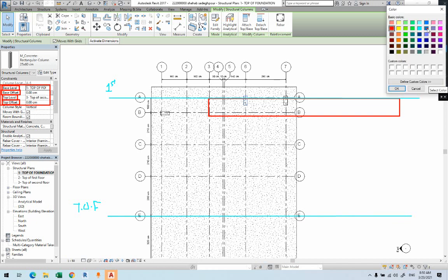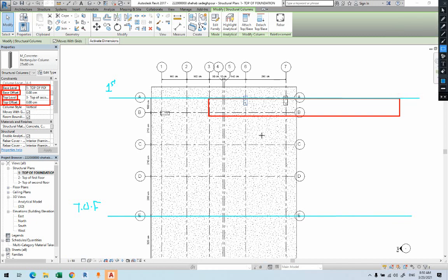Now when we create a wall, let's say the wall will start from the top of the foundation to the bottom of the beam, yes? Now, do I have any level for the bottom of the beam? Well, I can create it. I can add another level for this one. For each bottom of the beams, I can add a level. Or I will use offsetting, the top offset.